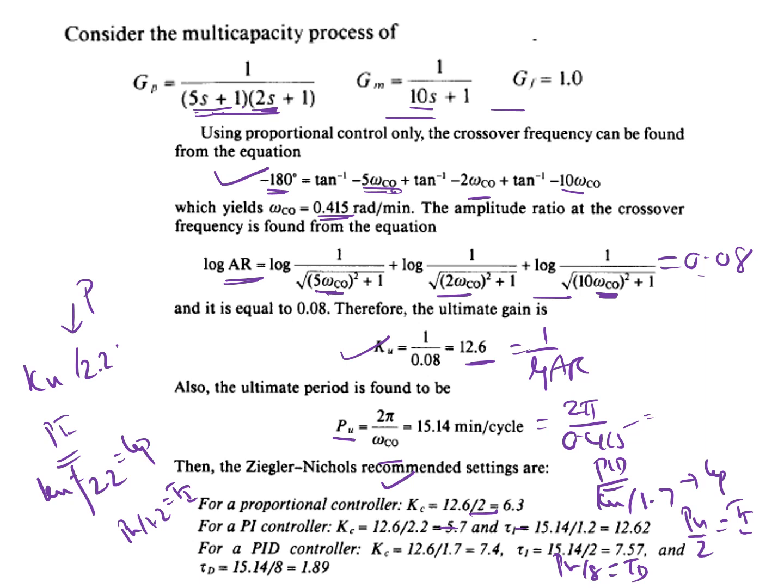So just we'll see the recap on that. In this unit we have studied various controllers, characteristics also we have studied. Then next one is we have fixed the criteria such as overshoot, rise time, and time integral performance error like ISE, IAE, ITAE. We have studied all those, and we have chosen the system like proportional controller is for liquid level process or gas process. Even PI control is for that process, and PID it is temperature process or multi-capacity. So once we fix a criteria, we can choose the controller.